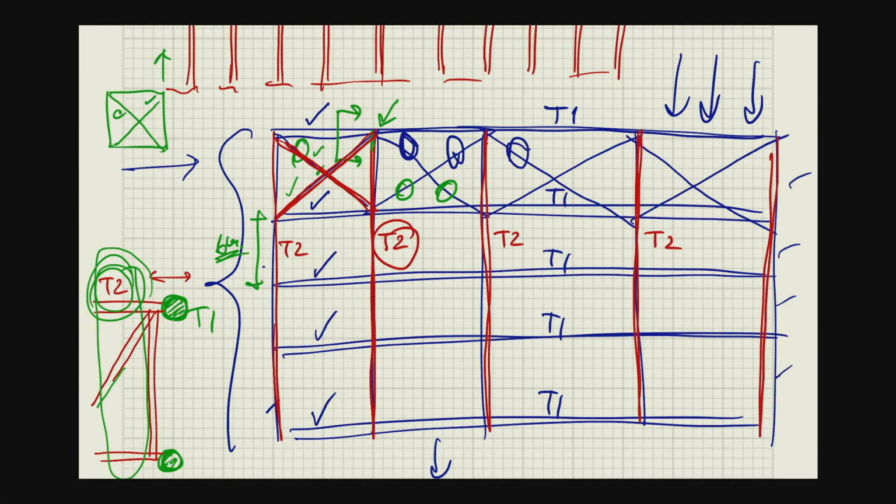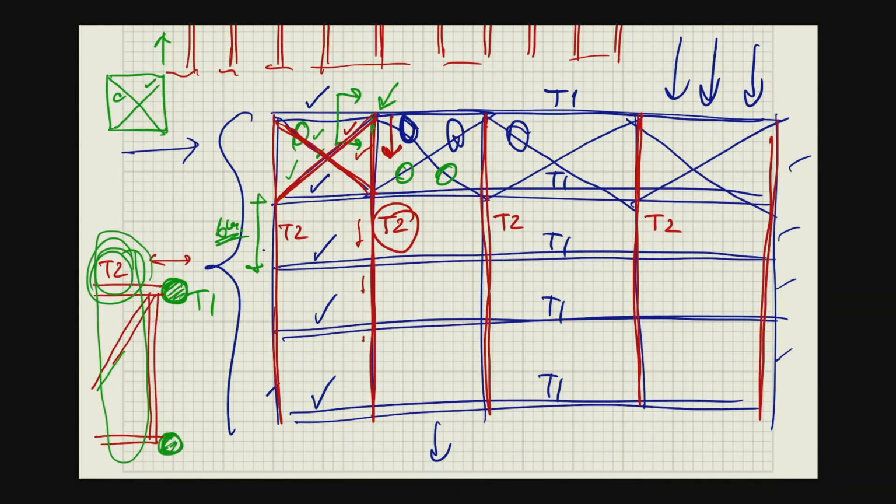And now the T2, how is it designed? As you know, the maximum force in here, you know the component in this direction. This component is going to be smaller and smaller as it goes far away, right? But you just design for 1, so you just design for this one. So the maximum orthogonal force in this direction is going to be used for the design of the T2. And the size of the top and bottom chord of T2 can be determined accordingly.